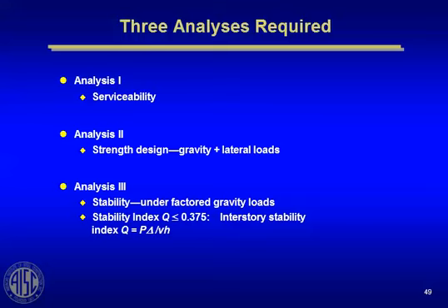You have a multi-story building, anywhere from 2, 3 levels all the way up to 60 or more levels. Every story has a Q value, a story stability index. And that story stability index is actually identified, for those of you that design concrete buildings, shouldn't talk concrete in here, but for those of you that use that other material, the ACI 318 code actually in Chapter 10 uses the term Q for the stability index.